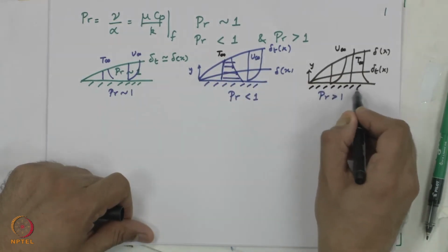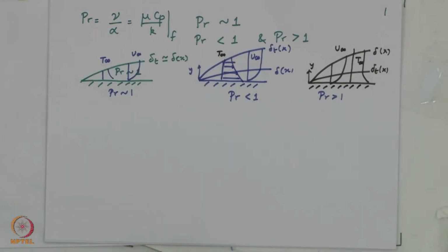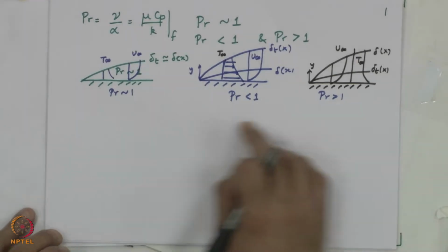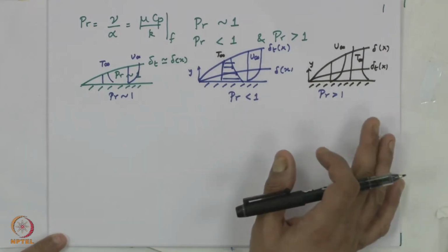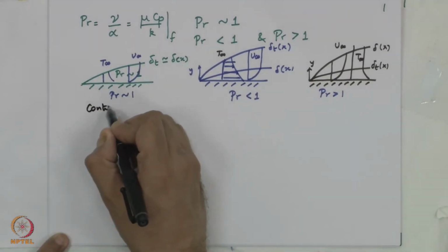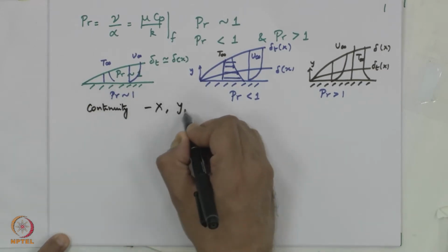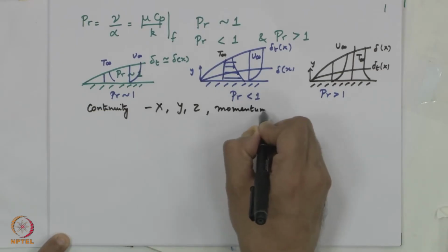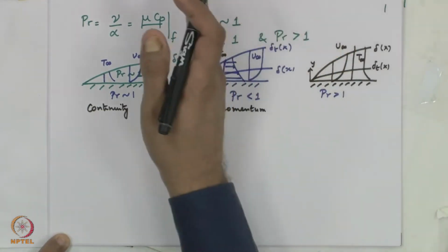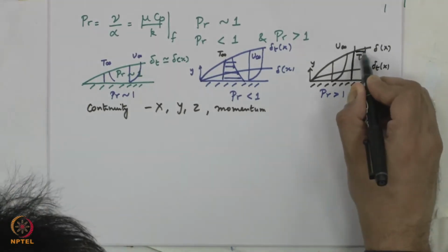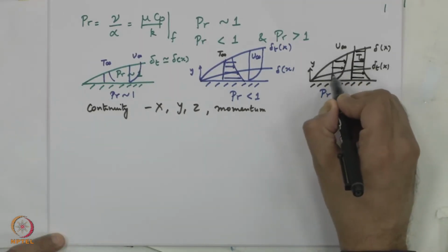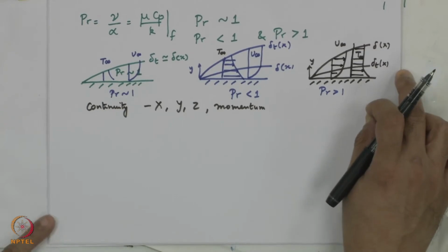Okay. Based on this, we said the governing Navier-Stokes equation, we wrote only the Navier-Stokes equation and we wrote one term of the energy equation which we have not derived at all, but simplification of the Navier-Stokes equation becomes very good when we split the flow into these regions. Therefore, instead of solving the complete set of continuity, x, y and z momentum equations in all their entirety in the whole flow field, which means y equal to 0 to infinity and all the way along the length of the flat plate, we will be able to solve certain simplified versions of the equations depending on where we are.